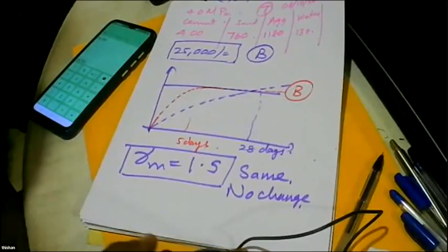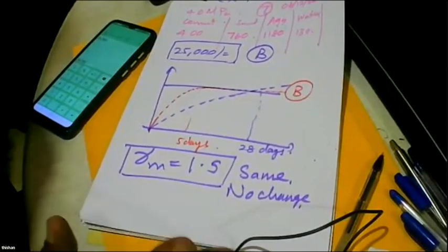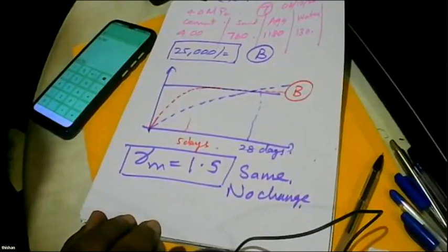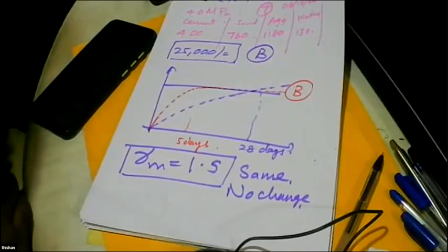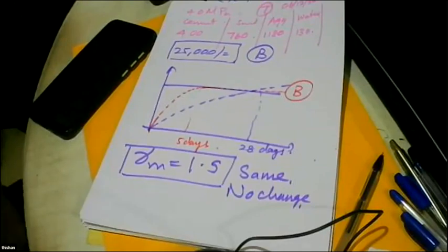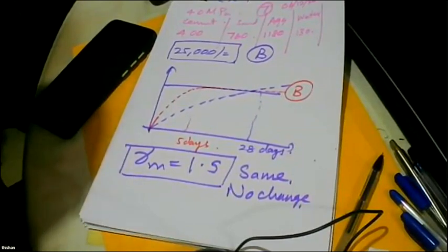You have to be vigilant and you have to think rationally. And you can do wonders with concrete technology. And you have to always look for the cost. Because we are substituting fly ash for cement, where fly ash costs only 15 rupees, whereas cement costs 40 rupees.